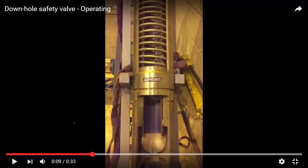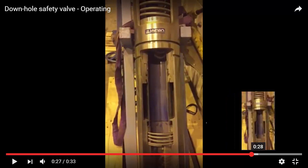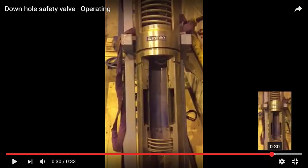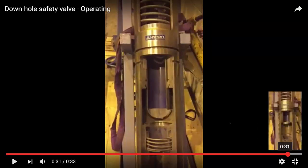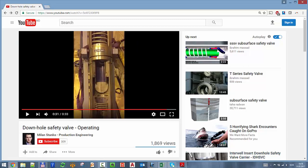You see the flapper here, it has a hinge below that you cannot see. When there is a loss of hydraulic power, the spring starts to push up and moves the sleeve up. That happens very quickly. The sleeve moves up, and then the flapper just closes. We will take a trip to the lab in the future.